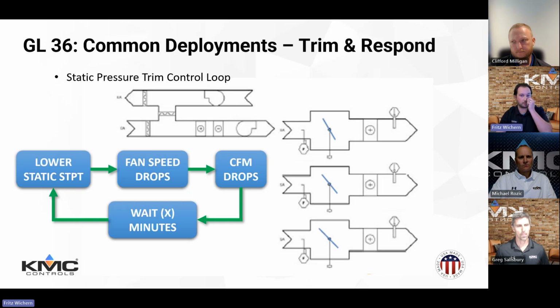And again, requests are submitted to the air handler from each zone. They're scaled by their importance multiplier. The air handler controller pulls those damper positions of all the VAVs and compares them to values indicative of a request for more static pressure. The system can only trim to a point, though, before the well of static pressure dries up, and then more supply is required from the air handler unit, so it can only go so far.